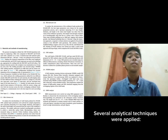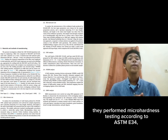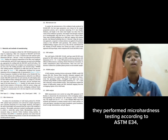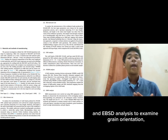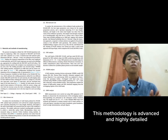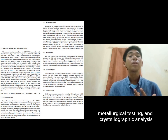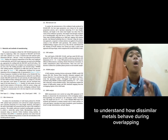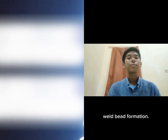Several analytical techniques were applied. They performed micro-hardness testing according to ASTM E384, FESEM imaging to study microstructure and surface details, and EBSD analysis to examine grain orientation, texture, and boundaries. This methodology is advanced and highly detailed because it combines additive manufacturing, metallurgical testing, and crystallographic analysis to understand how dissimilar metals behave during overlapping weld bead formation.